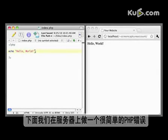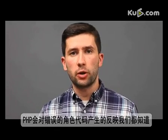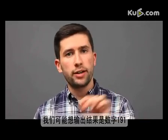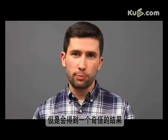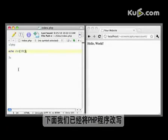Now let's make a very simple PHP file to put on our server. It's just one line of code that says to respond with the ANSI character corresponding to the value of 191. Sending the response as an ANSI character will help us to keep the code simple on the Arduino. If we were to send the numbers 191, our Arduino would have to interpret that string into an integer before it could evaluate it.